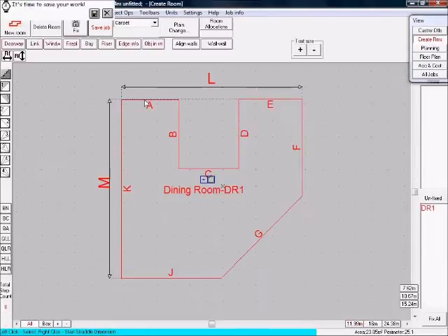Now we're going to enter measurements for our space. The general rule is to enter the measurements for all of the straight walls first. This way, the system will often deduce the measurements and slope of a diagonal wall for you. Firstly, I am going to align walls A and E. This way, the system will begin to deduce measurements for us straight away.